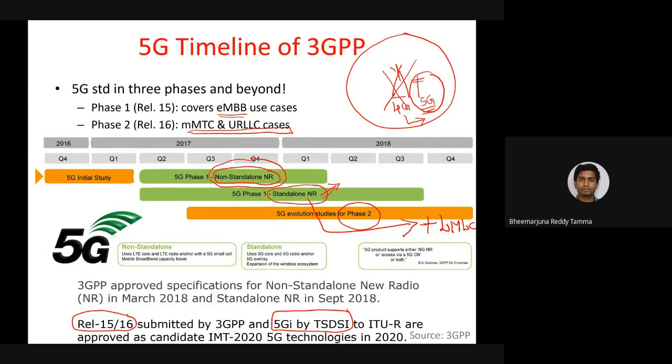So if you put new technology where the cell radius itself is less than 2 kilometers, then tomorrow no telecom operator can try to deploy a massive number of base stations, because the coverage of each cell is only 2 kilometers. So initially TSDSI asked ITU to have an inter-site distance of 12 kilometers, but there was a lot of resistance. Finally, it was agreed that yes, we can have cells which are larger than 2 kilometers. Finally, it was agreed that 5G will support an inter-site distance of 6 kilometers. That means I can have base stations deployed which are separated from each other by 6 kilometers. But without this LMLC, it is only 2 kilometers that base stations can cover.